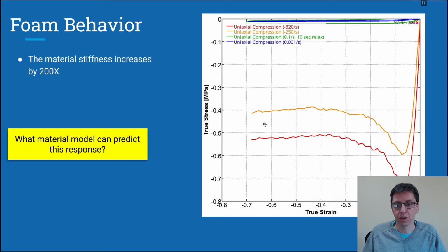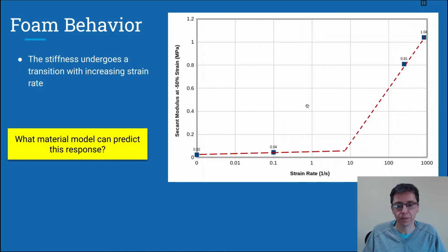So in this case, we performed some high-rate impact test experiments using a drop tower, and we measured the stress-strain response in addition to the two slow rates at these really high rates. Look at this. It's unbelievable how different the stress-strain response is at the high rates compared to the slow rates. Clearly, this is something you wouldn't easily predict unless you perform the experiments.